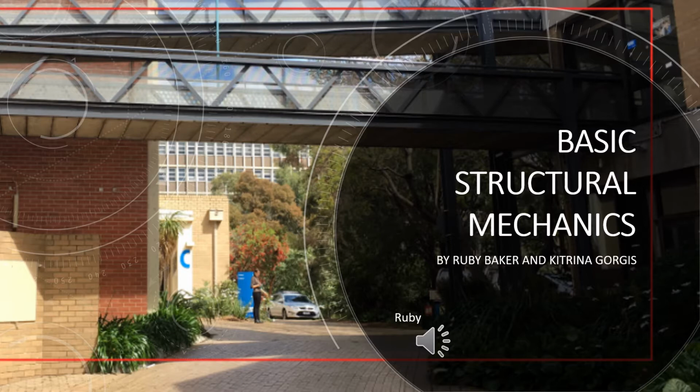For all phases, the phase before it is essential to the calculations and equations for the next. Phase 1 uses mass and volume of specific parts to understand overall volume and mass of the structure. Phase 2 uses mass and volume plus the forces of gravity to determine reaction forces upwards and the uniformly distributed load, UDL, as well as the dead and live load. Phase 3 then takes the UDL and the reactions to determine the bending moments and shear forces of the bridge, specifically in parts holding the weight of the traffic in the S-beams.